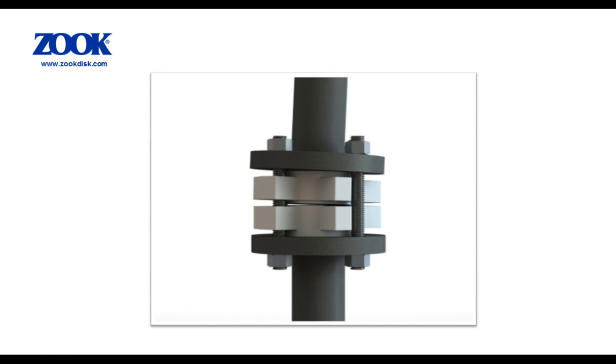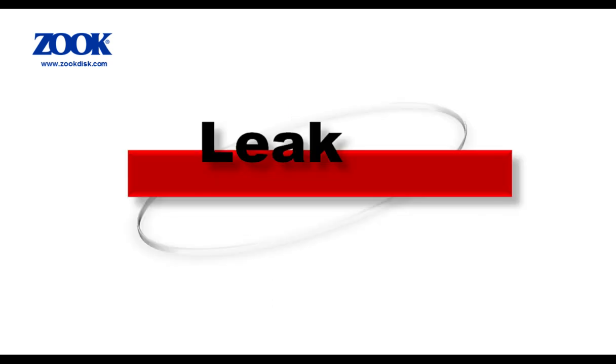Misaligning holder and disc components or incorrect torque patterns can also cause leaks. Similar to changing a tire on your car, it's important to gradually increase the torque around a flange in order to provide equal loading to the assembly. Misaligned piping like that shown in this picture or incorrect flange torque can result in multiple leak locations across a rupture disc assembly. Some manufacturers offer pre-torque holders, which allow the installer to preload the disc and create a leak-tight seal prior to field installation.